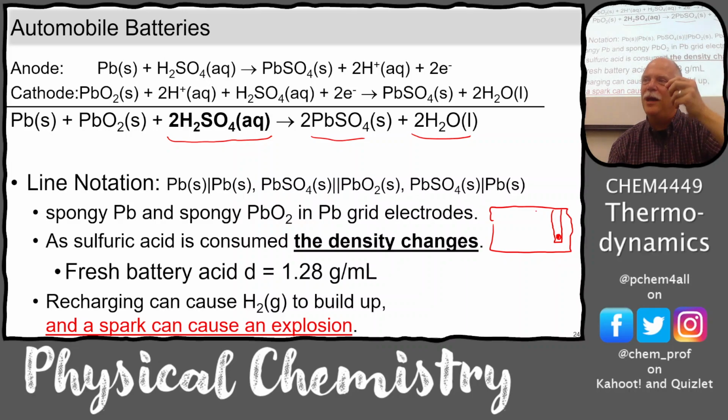And you look in the top of the battery, it looked like a little light, but it wasn't a light. It was just a fluorescent bead. You could see it when it was fresh. And then when it got to be more water than sulfuric acid, that bead would sink. And so you look in the little sight glass and you couldn't see anything.